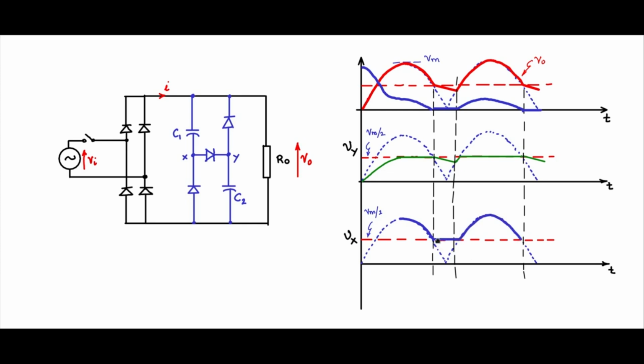And this point will be the 0 point because during this time this diode is conducting. When the capacitor is discharging during this time, the diode is conducting, and then you will have a horizontal. So this is the type of waveform that you will see for Vx and also across these diodes.